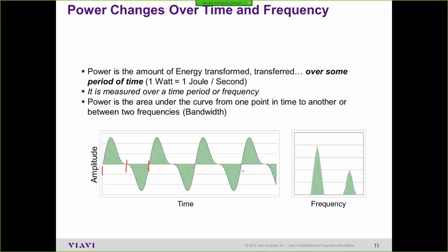So when you're discussing power, you really need to understand, well, what's the time period? What's the bandwidth? And especially, you need to understand the bandwidth on a spectrum analyzer. If you don't understand the bandwidth of an RF power level, you really don't understand the number.